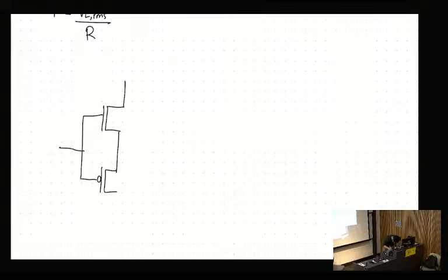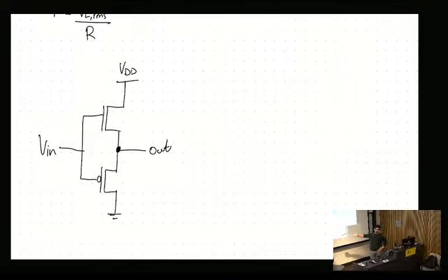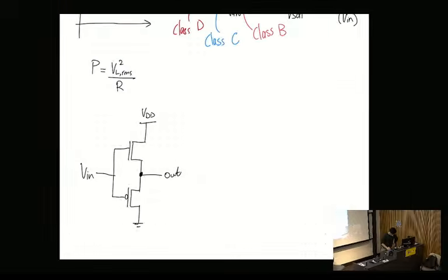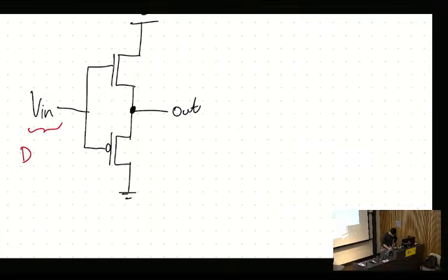So often what we have is something that looks like this. So NMOS. And we send the input signal to both of these. Let me take our output there. Now, I'm just omitting things like the load and all that. That's there. And this signal is always comprised of VDC plus VAC. So the DC biases it into the operation, into the region we want, and then the AC signal just fluctuates it around that signal. And the amount you can fluctuate this AC signal, I'm only mentioning this because I saw it in a past paper.